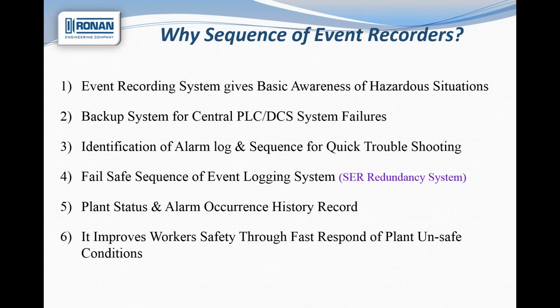So why a sequence of event recorder? It's giving a basic awareness of a hazardous situation. It's a backup system to the PLC, independent of the DCS. It gives identification of alarms, quick troubleshooting, fail-safe sequence, plant status, and it can improve worker safety.